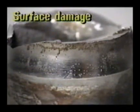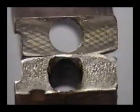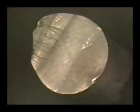Another source of stress raisers is surface damage. Improper assembly practice, rough parts handling, wear, corrosion, etc. can create this damage. We may need to compare failed parts to good parts to determine if an abnormal surface condition exists. The connecting rod parting face on the top is normal. The one on the bottom has fretting corrosion, an abnormal stress raiser. This bolt contains a fatigue fracture. The beach marks lead us to the initiation site, which shows no bullseye, pre-crack, or contour change. A closer look reveals a dent at the origin. This surface damage caused the failure. We now need to discover how the dent got there.